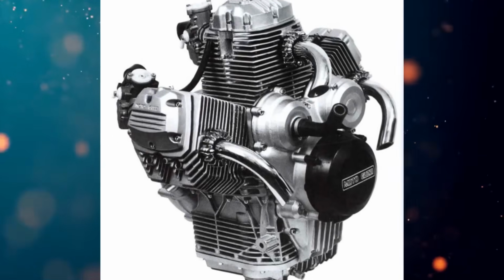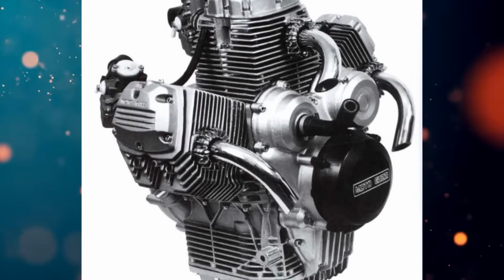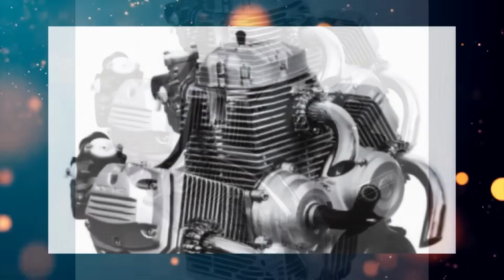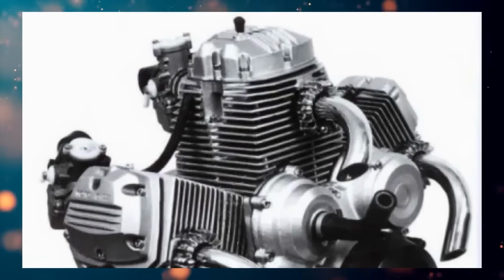It had a displacement of 992 cubic centimeters. The cylinders were set at an angle of 65 degrees to each other. The valves were operated by a cam mechanism in the crankcase and push rods going to the cylinder head.